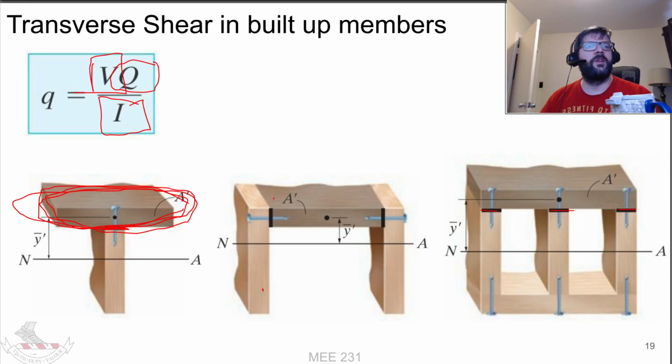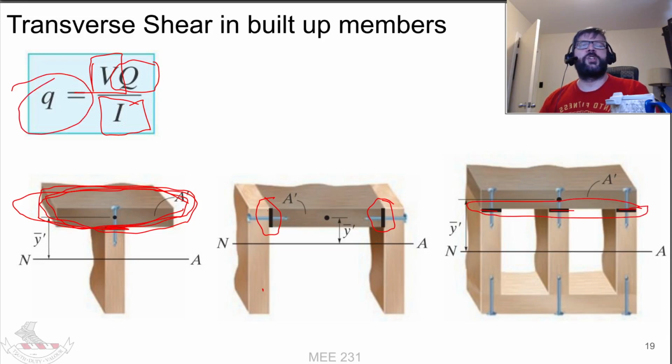If you're using, in this instance, two sets of fasteners, then you divide that by 2, and the same here. This formula gives you the overall shear flow you need to resist, and then you divide it by 3 to give you the shear flow that needs to be resisted per each set of 3 fasteners you're using. So yeah, we'll do an example here.